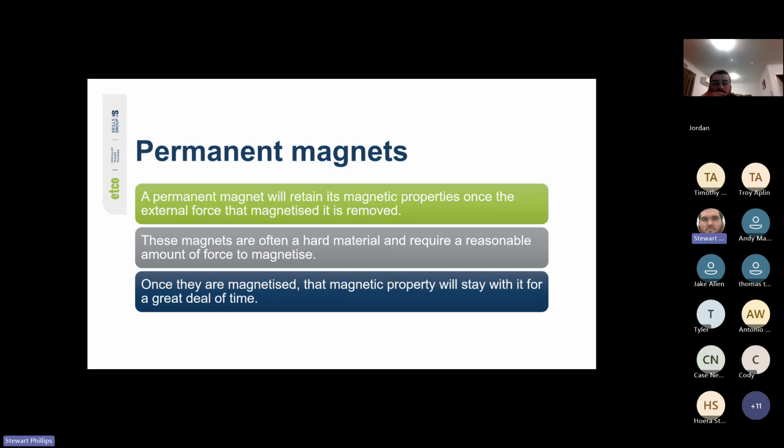Yep. Some examples of non-ferrous metals: aluminium, copper is technically non-ferrous, zinc, lead, nickel, titanium, and precious metals like gold and silver. They are known for malleability, corrosion resistance, and high electrical and thermal conductivity, but not very good for magnetism.